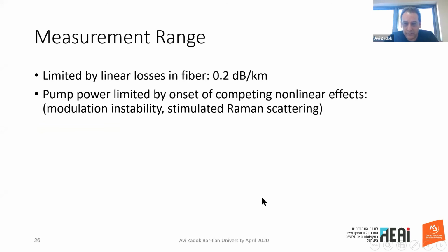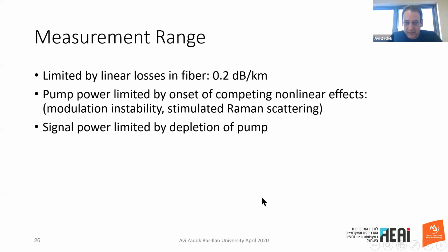And in order to compensate for these losses, one needs to launch pump power levels that become stronger and stronger, but there is a limit to that. If we attempt to launch pump powers beyond reason, then competing nonlinear optical effects kick in and eventually restrict our measurements. Also, the optical power of our signal wave in the opposite direction is limited. If the signal is too large, then its amplification would eventually eat away the entire power of the pump, and this is not very advisable.